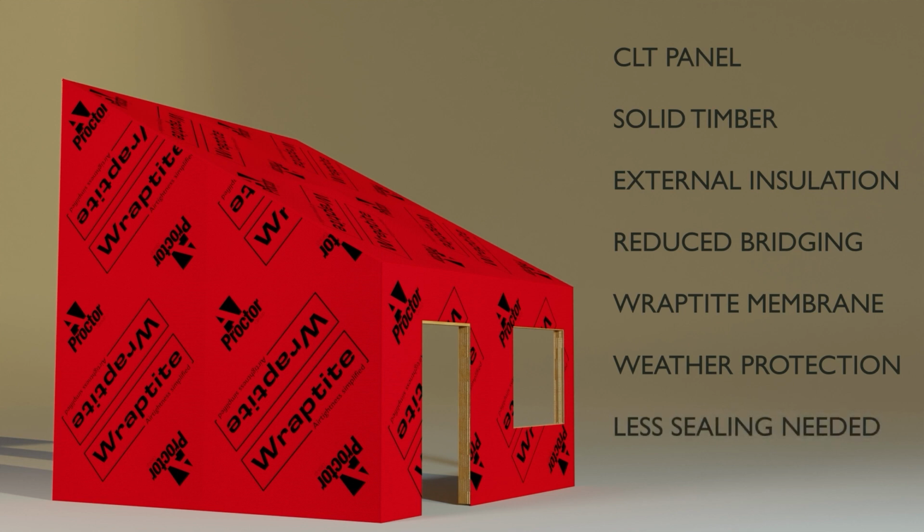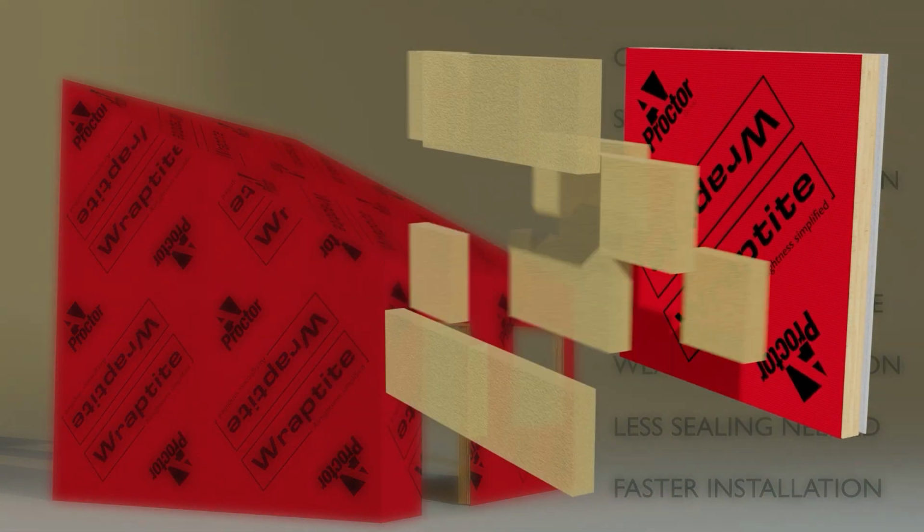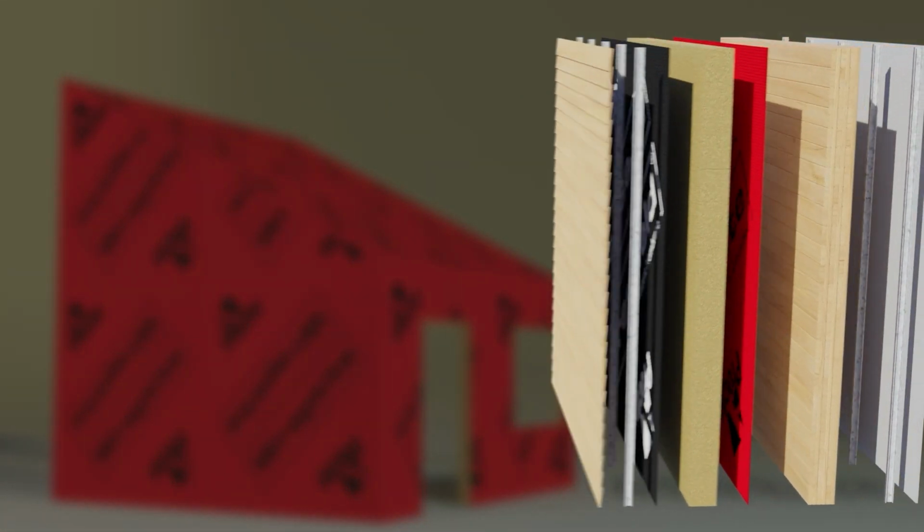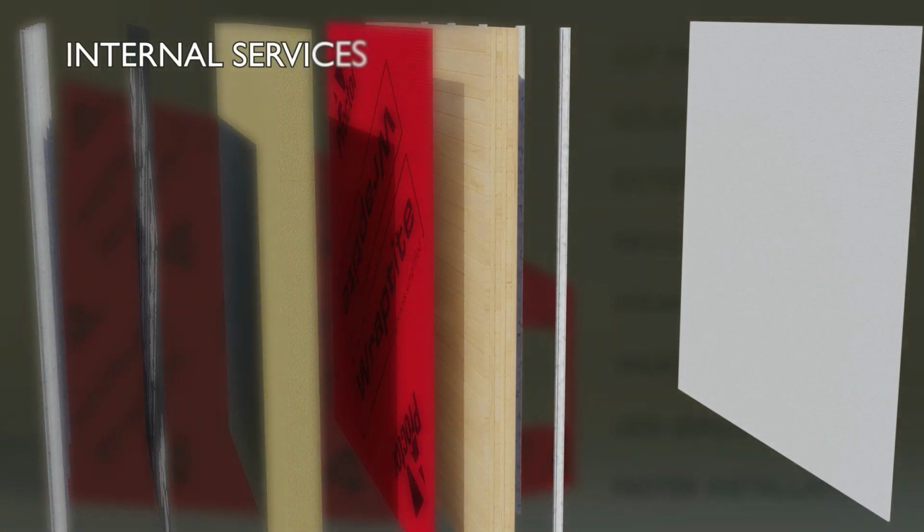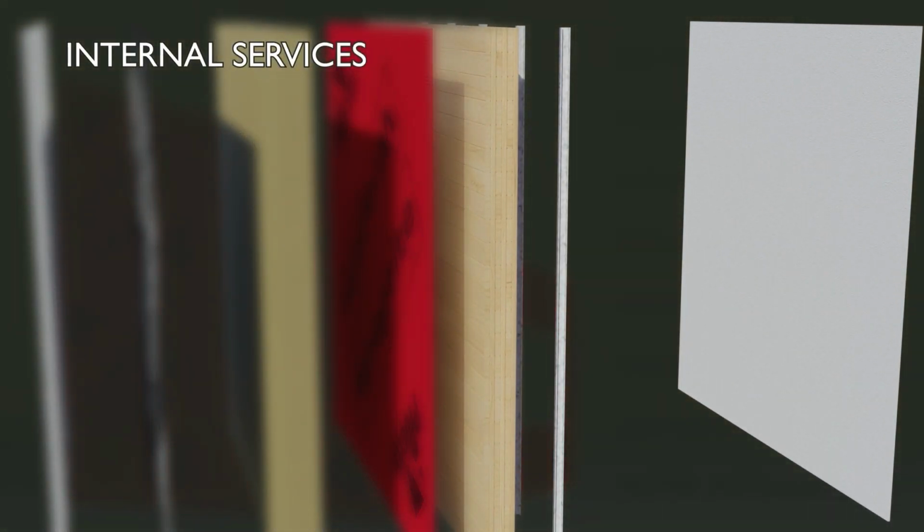Installing the air barrier in this position means there are a lot fewer complex seals and junctions required to work around internal walls, floors and other structural elements. This means ensuring the membrane is well fitted with good seals at all joints requires a lot less time and effort than if done internally. Internally, services can also be run wherever is required without risking damage to the air barrier.